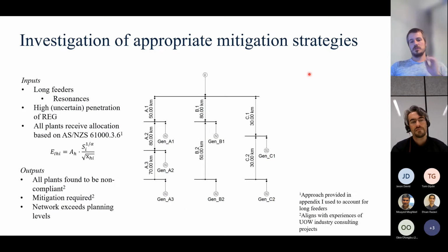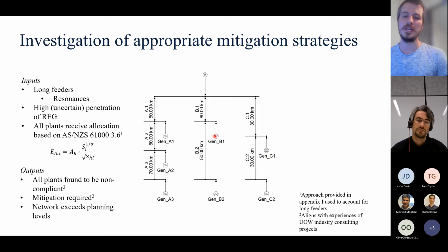Yeah. So the package that we used was PowerFactory, I think, was question number one. And as we've been saying, it's RMS, it's steady state, it's long-term kind of stuff. We're not looking at transients or anything like that that would require something like PSCAD. And the representation of the inverters themselves were gained from manufacturer data. And don't worry, I understand that I've just told you that what they do is really inaccurate, but it's the information that we've got at the moment. We also just need to feed in an impedance representation, really, of the generator is the most important part for these sorts of things.